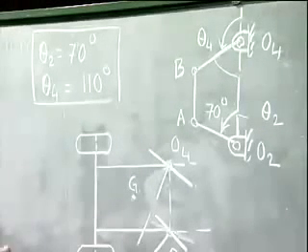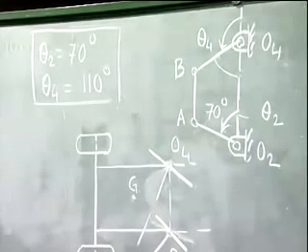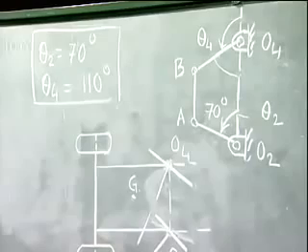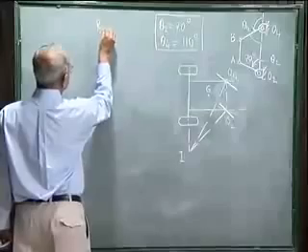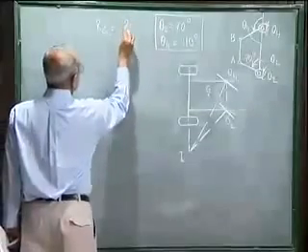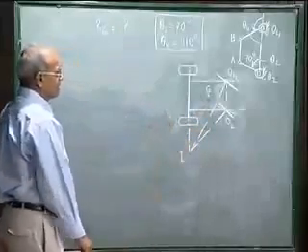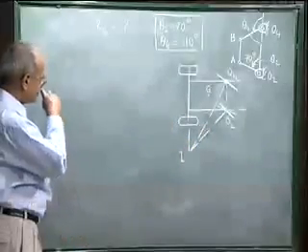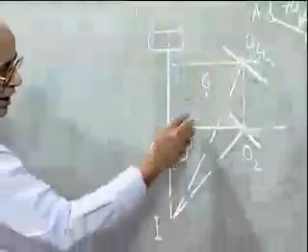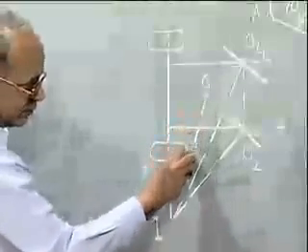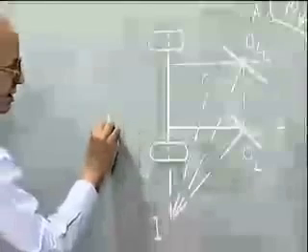Symmetric linkage takes care of the right hand and left hand turn identically. So we are left with only one more accuracy point. Let me take it as Rg, for which value of the radius of curvature of this center point G I must satisfy the requirement. And let us say the wheels have to rotate for that value of Rg.